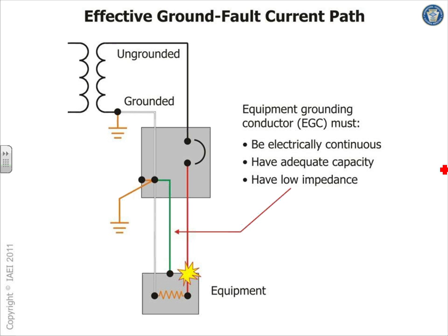This is just to be electrically continuous, guys. When you have an equipment ground conductor, we don't get into sizing it a lot. The NEC code book makes it easier for us. All you have to do is go to 250.122, and ask what's your overcurrent protection device? Here's the conductor that goes with it. As long as you use this table, the conductor will do two things.